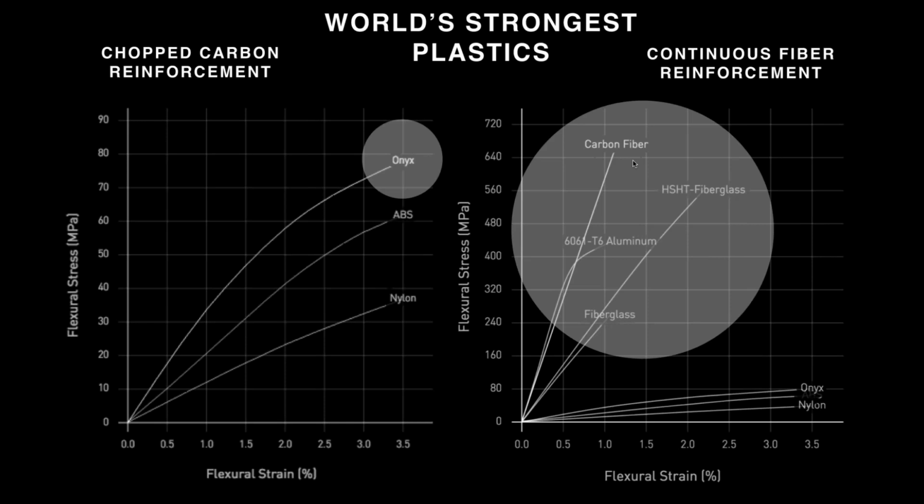In terms of both flex and tension, that's going to be about the same flexural modulus as 6061 T6 aluminum, which unlocks all these applications where not only am I using this for my end use part, but I'm also considering using it for applications where I'm doing work holding, tooling, fixtures, and jigs. So that opens up a lot of capabilities. Worth noting that carbon fiber is also going to have a higher ultimate strength and better fatigue resistance than aluminum. So not only is it cheaper than those aluminum jigs, but it's also going to last longer in an industrial setting.